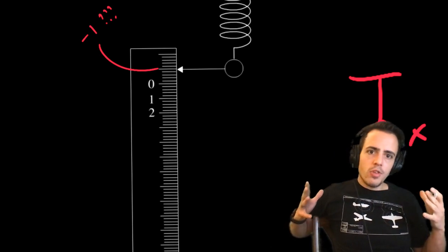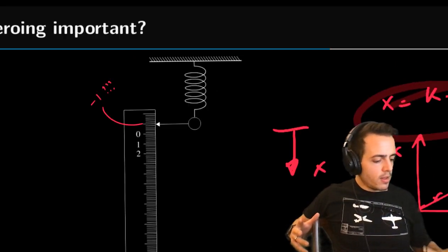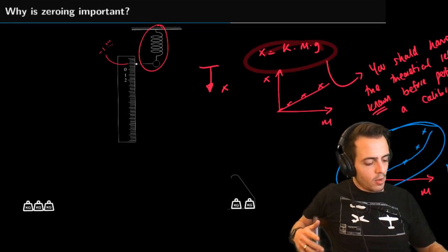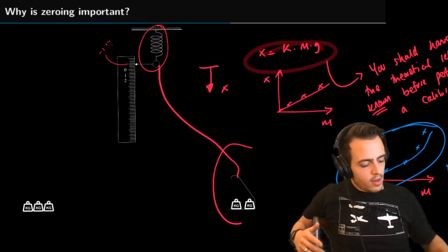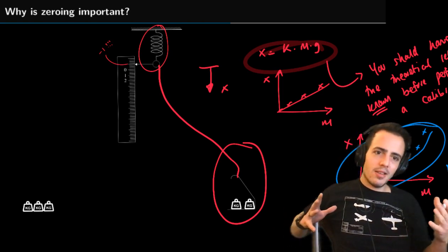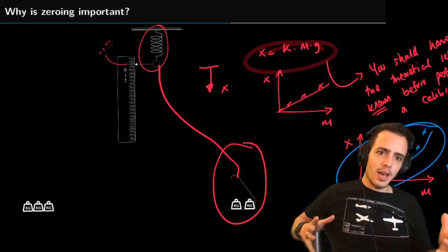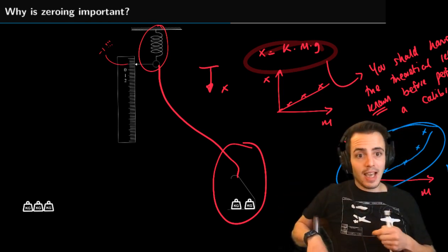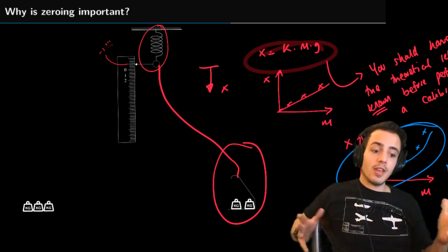So what we've just done here is we've said, okay, I was trying to calibrate this device on its own, but what I was actually doing was calibrating this whole thing coupled together. And we can appreciate that if we're using a transducer in an experiment and we don't pay attention to what the 0 is at the beginning, then we could get the incorrect answer.